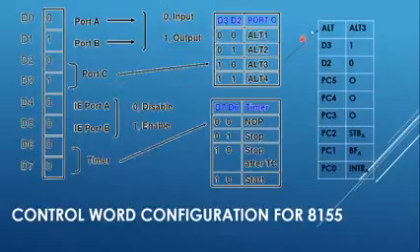In this mode, PC5, PC4, PC3 act as output pins. PC2 is strobe, PC1 is BF signal and PC0 is for INTR. End of conversion is connected to PC2 and buffer full is connected to output enable.